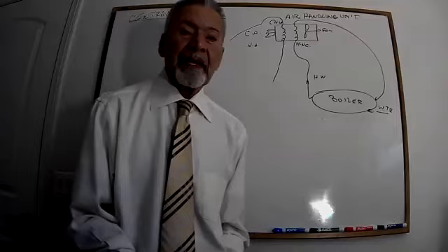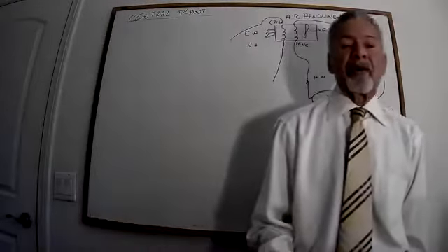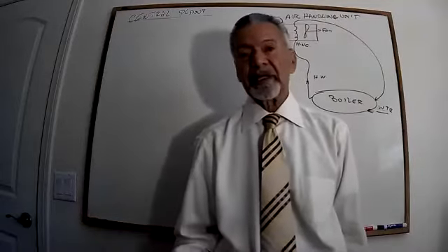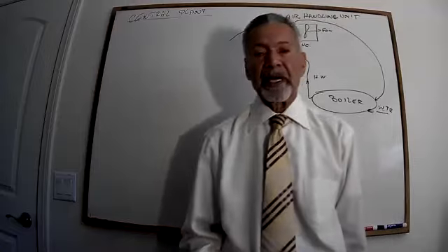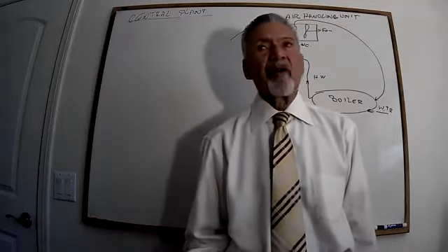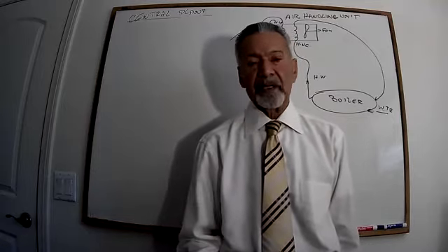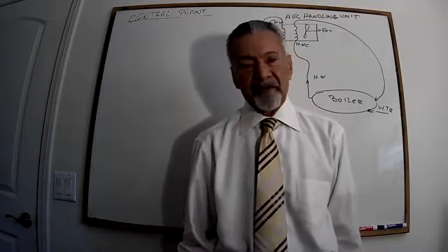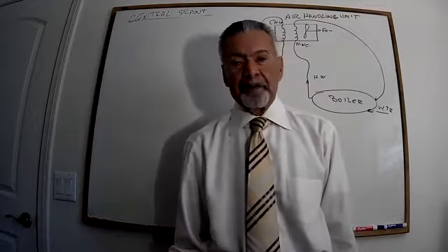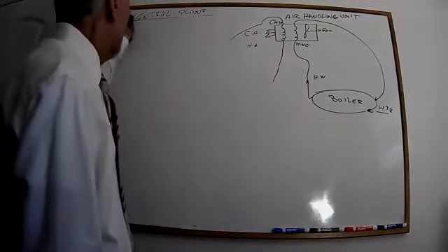But in a home, it's always designed to constantly have a 10% minimum outside fresh air. In a commercial building, it's 20% outside air. It keeps coming in. So using water for smaller commercial buildings or smaller homes is not an efficient way of doing it. Not at all. Did that answer your question? Yep, got it. Thank you very much.